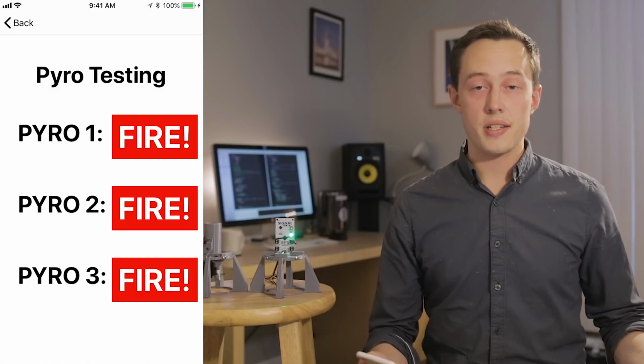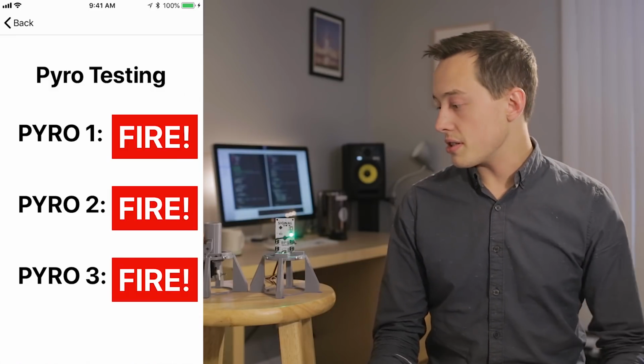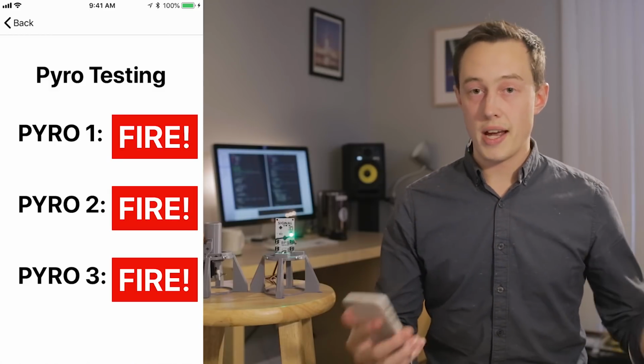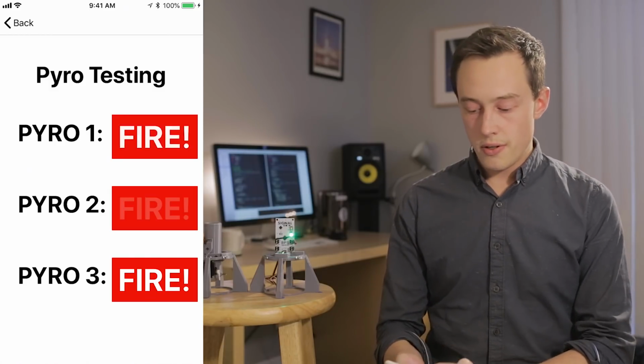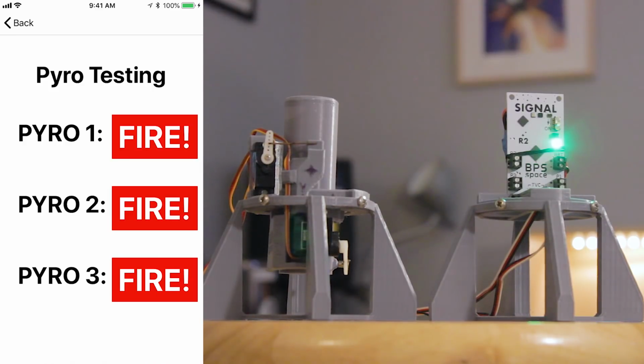This is for ground testing your ejection systems, especially on larger rockets. This is important. It's good to do ground tests to make sure your ejection system actually works. So, you know, it's safe to do this because nothing's connected, but traditionally you'd want to be outside and a little further away.